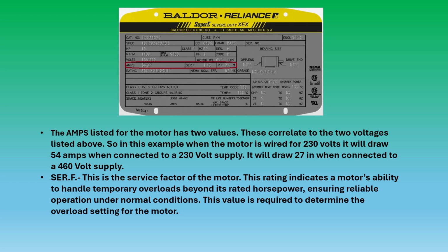Now, just so we understand here, a motor will try to draw as much horsepower as it needs. You can take this 20 horsepower motor and attach it to a pump or other piece of equipment that is requiring 30 horsepower, and that motor will output 30 horsepower. It will do so up until it exceeds its torque requirements. Once it reaches that breakdown torque, of course, it will come to a stop. But by doing that, you are seriously overheating the motor and you're going to shorten the lifespan of that motor.